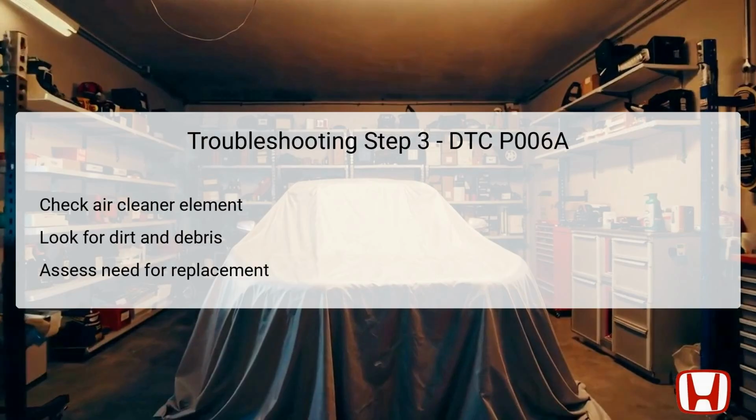This can result in miscalculations regarding air volume, impacting the engine's performance and fuel economy. If the air cleaner element shows signs of being dirty, it will need to be replaced promptly. If it appears clean, you will proceed to the next step in the diagnostic process. Regular maintenance of the air cleaner is crucial to keep the engine running smoothly, and a dirty filter is a common issue that can lead to further complications.